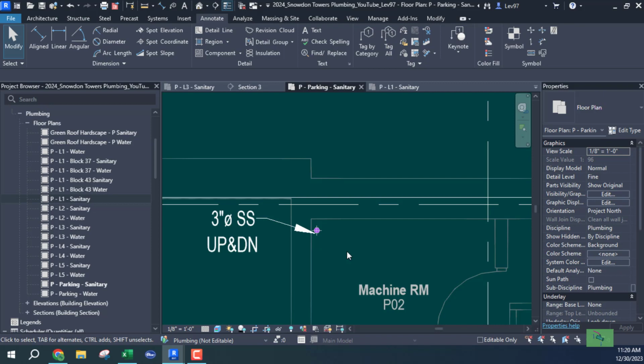You have to use some caution when you're doing that type of copying. I don't like to copy because you can actually copy an entire plumbing system from one floor to the next. But I wouldn't recommend it, because a lot of times it doesn't connect. Everything has to be in perfect order if you're going to copy piping material, like an entire system.